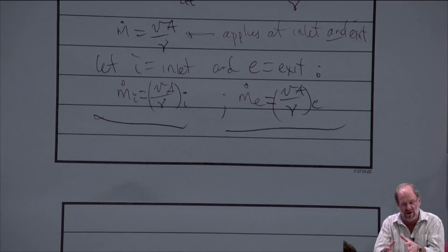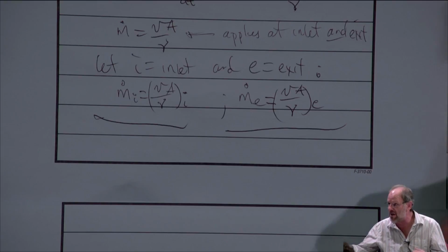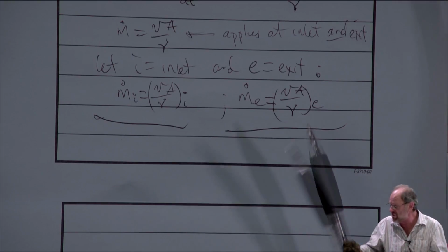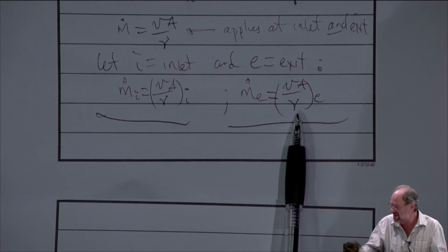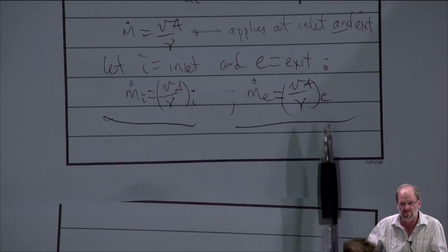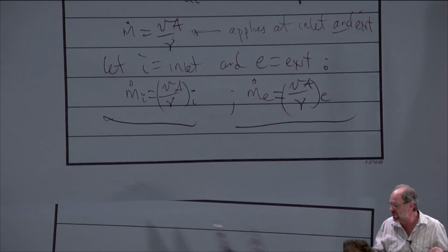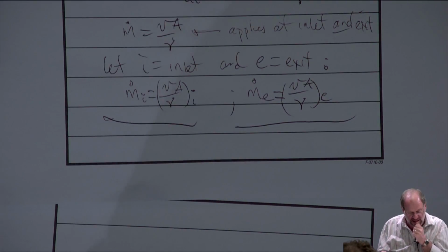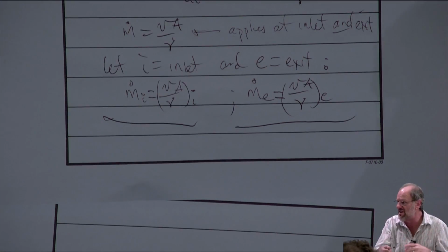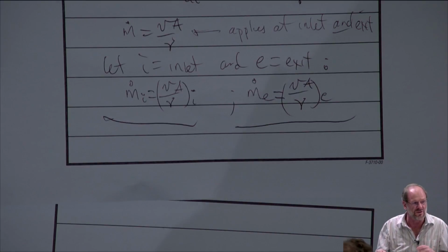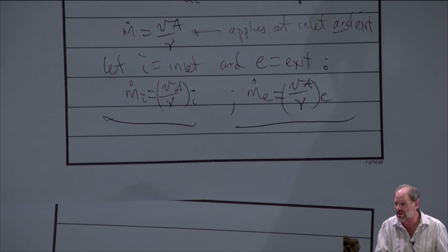I mean, if we have water going into a pump, and then we add work to that water in the pump, it's going to have an increase in energy. It's definitely going to have a different thermodynamic state going out as it does going in, right? So there's no reason to assume that since the state changes, any of the properties are going to remain constant; they're all going to change. So you never want to make that mistake in this class, unless you're told specifically that it's an incompressible fluids problem. Some are, most aren't.